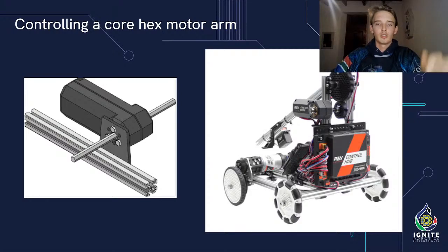And it's something you can tune. So a good place to start is just a lower number so you can see how much it moves. So you can say delivery is 200, and then of course you would have int collect or the start position, which would be 0. So in theory you don't need to store this in a variable, but it just makes everything a lot cleaner. So if we go back down here, now we've got our positions for delivery and for collect in encoder ticks. For A, we wanted to move to collect.